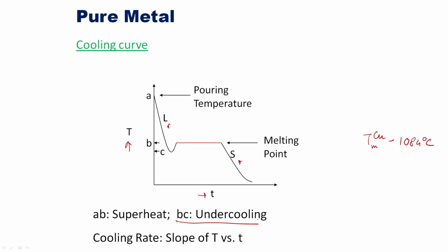So, this is from a lay person's point of view. Nucleation, as you know, is not a very easy phenomenon to understand. Basically nucleation means the temperature goes down and you are undercooling, giving the system a certain amount of energy to form the nucleus or nuclei. After the solid has nucleated in the liquid, you can easily consider even the water and ice system. You take water and start cooling down; at 0 degrees Celsius, water will never transform to ice. You have to cool below 0 degrees Celsius to form ice crystals inside the water.